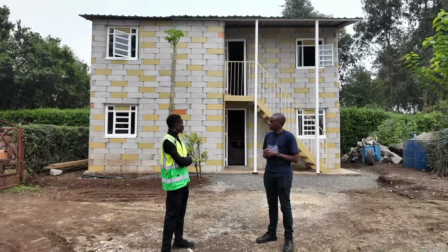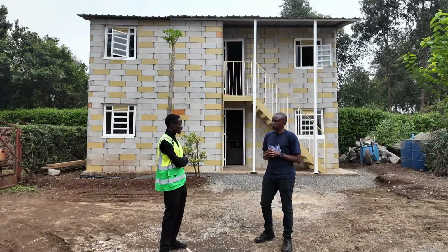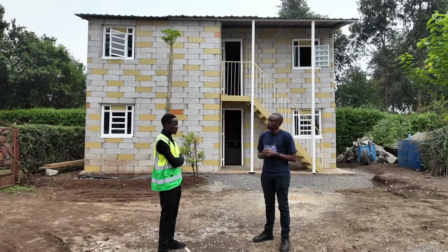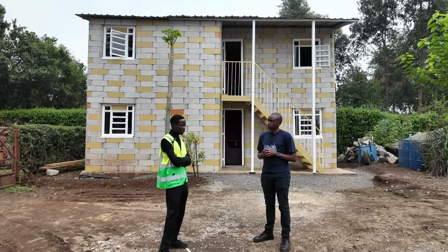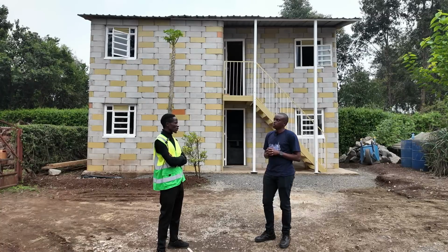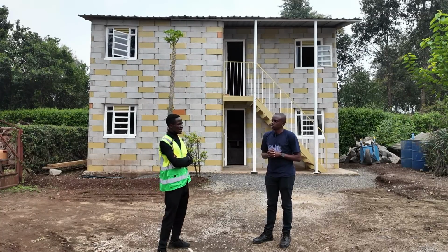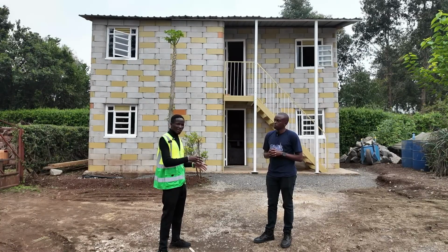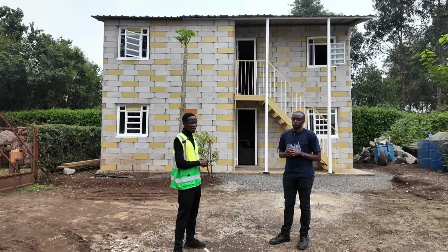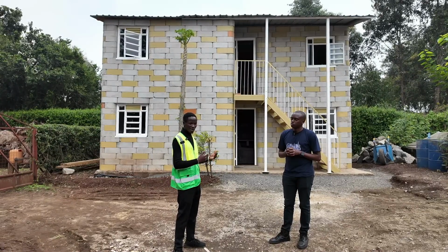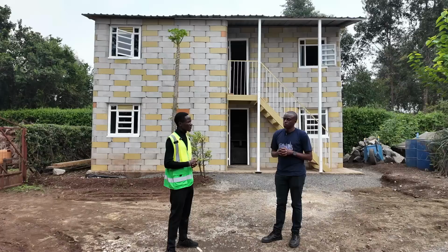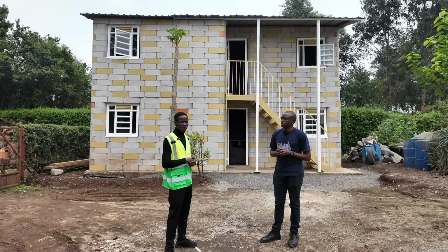So in Kibra, we've had people who've bought blocks, they've done some perimeter walls, they've done some stalls. So it is very, very adaptable to any person, regardless of the skill that you have, because it's just a plug-in system where you just stack the blocks all together. As long as you understand that the first course should look like this, the next course should be in the opposite direction, to remove the aspect of straight joints within the blocks.